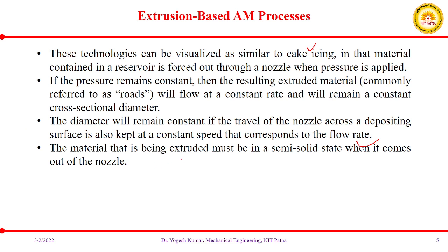The material that is being extruded must be in some semi-solid state when it is coming out of the nozzle. Yeah, it is a mandatory thing because we obviously cannot deposit the solid wire or bar on the build platform. We have to heat it.